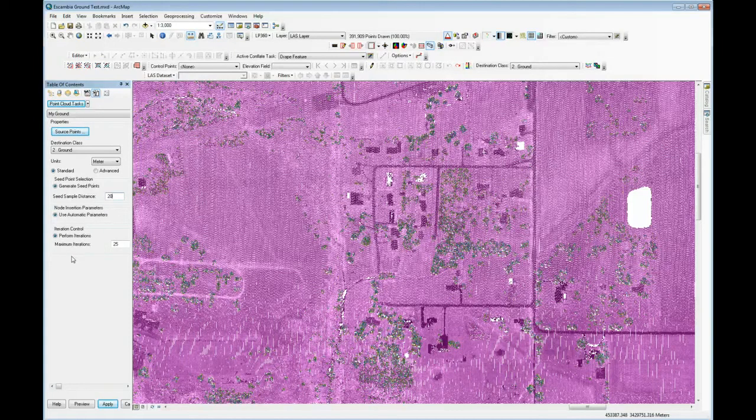When we've checked all of the points in the surface area that we're trying to classify, we'll take a second pass through it. That'll be iteration 2, and so forth and so on. We stop doing that process when we've either hit the number of iterations that you specify as max iterations, or no more points were added to the ground surface in the previous pass.